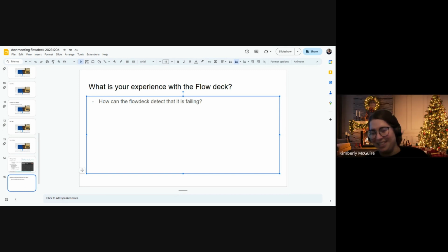Yeah, most times true. I think one of my first works was to actually put a camera on it and use optical flow divergence, which you don't get from the flow deck sensor. It doesn't know if it's yawing or not, and I forgot to mention that. If you yaw quite a lot, then you will also get quite some drift, because the flow deck is not able to distinguish between flow that's created by it turning around.